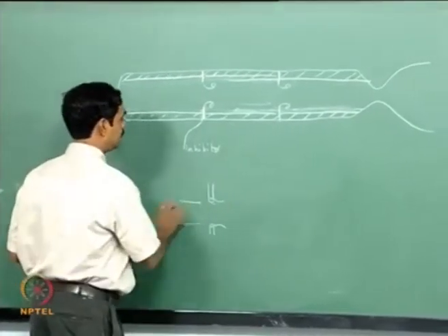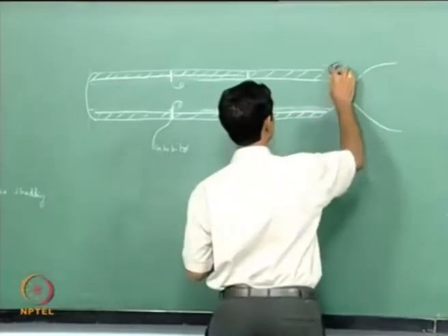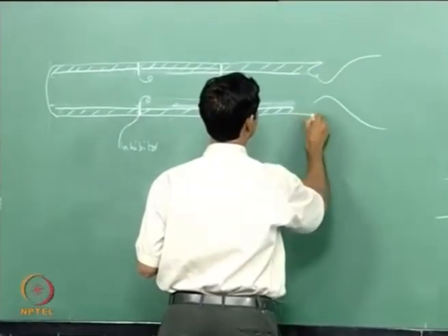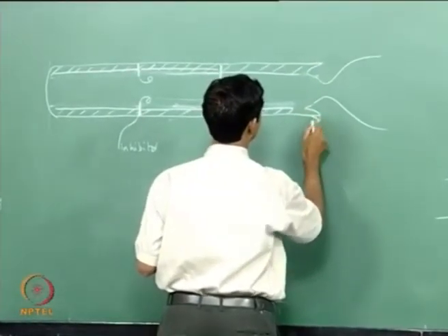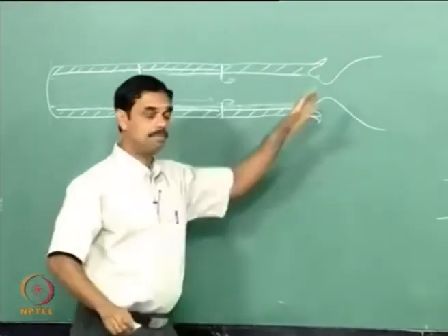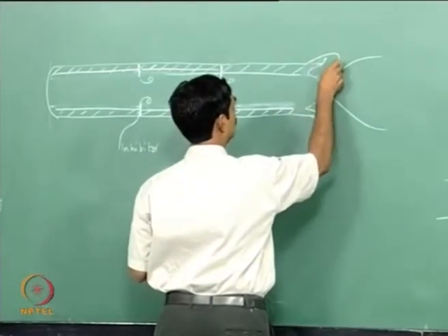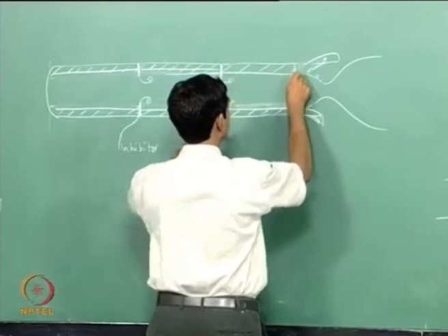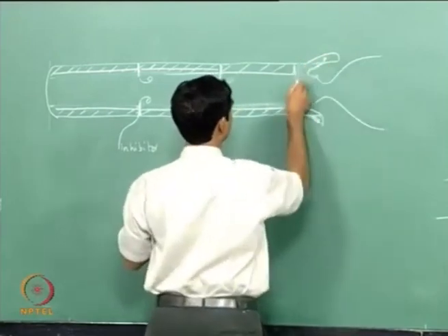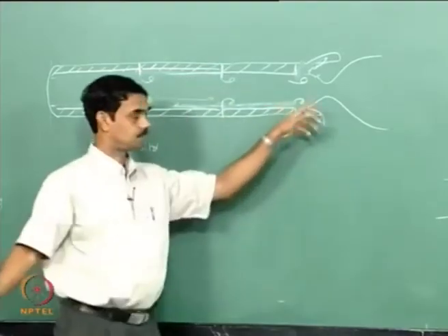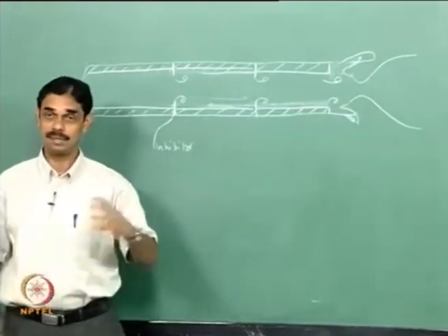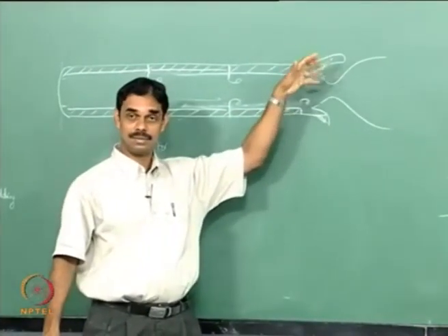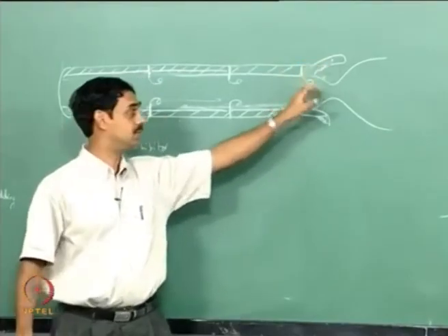And yet another possibility is if you have a nozzle which has a bucket-like structure. Because of the gimballing mechanism there will be some space provided here. So this is where the gimballing mechanism is, and the vortex will travel over this cavity, and then it is like my blowing over the bottle. This works like a Helmholtz resonator, and it creates the sound here as the vortex goes over this.